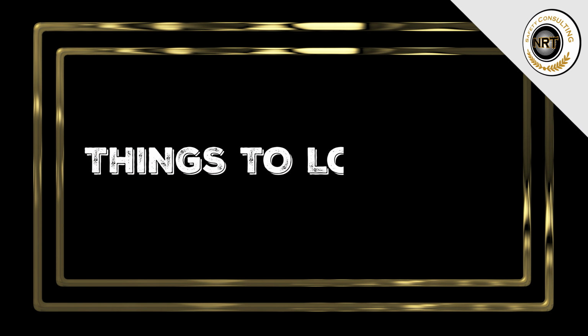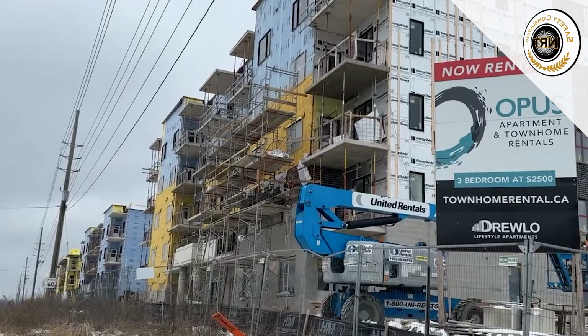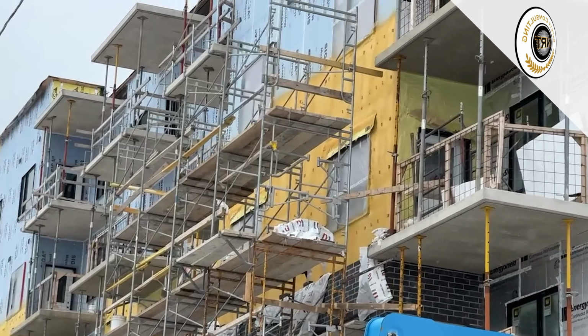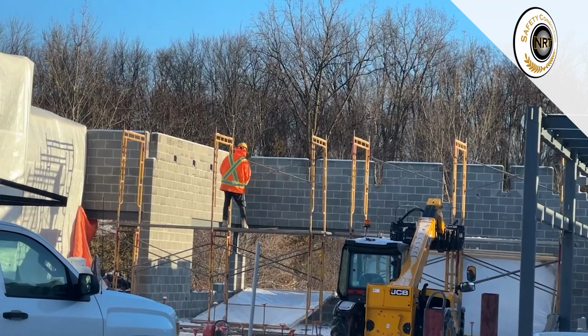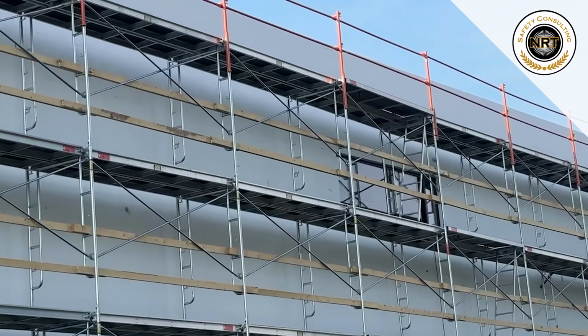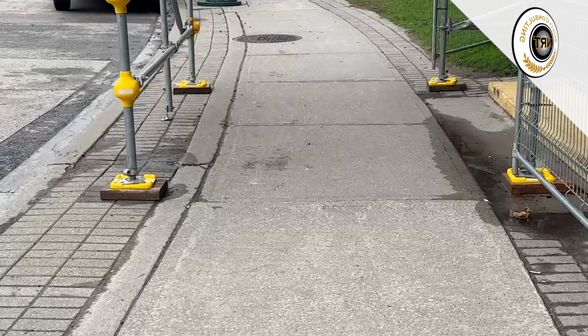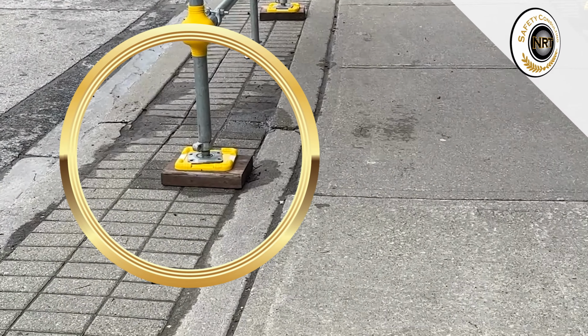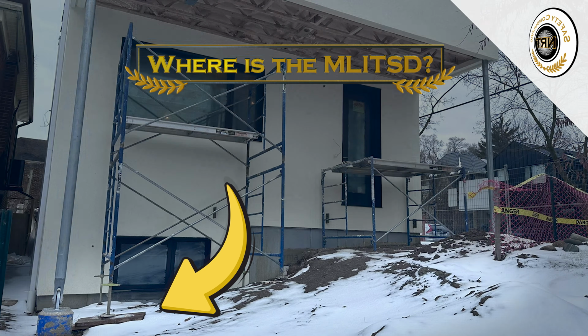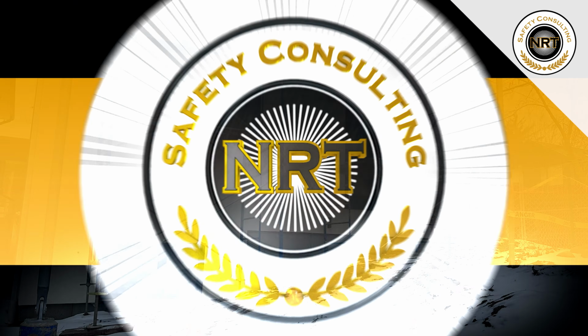Things to look for: frame and structural integrity. When inspecting scaffolding frames, ensure that all vertical and horizontal members are properly erected and securely fastened, with no missing components or visible damage. Check that base plates are secured to rigid sills on level surfaces without signs of settlement or deformation to prevent inadvertent movement as required.